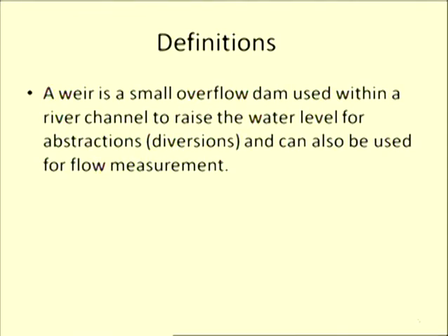These weirs are created. This is basically a small dam kind of thing on a foundation. It would have a height, and then it would have a breadth, and water is flowing above it. I would show you sketches of how it would look, but the major purpose of construction is that we can measure the flow in actual channels. When we obstruct the flow, there would be a rise in the water level upstream.